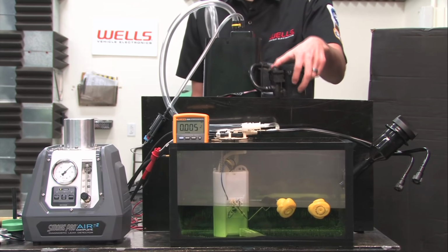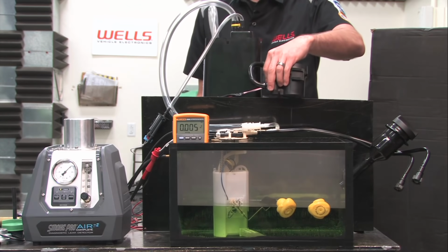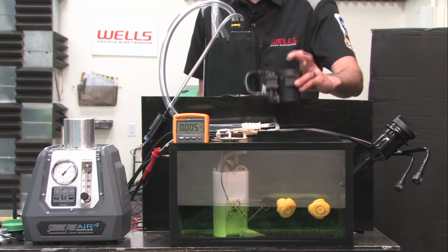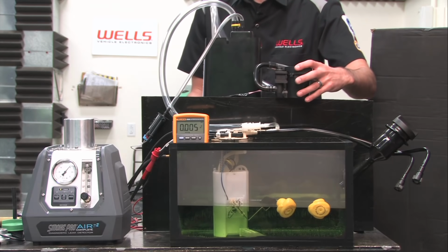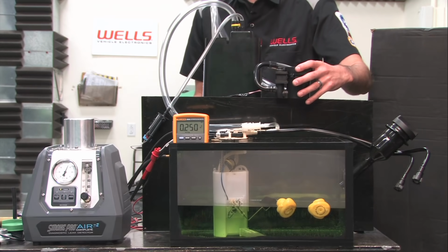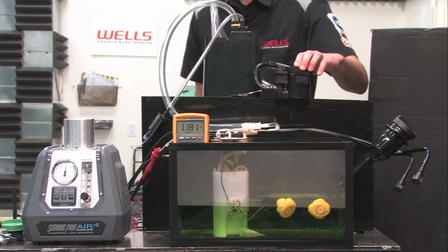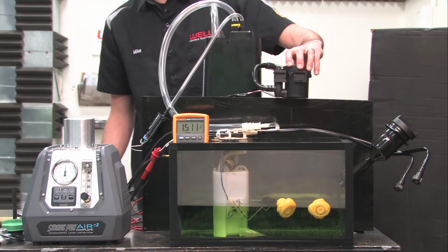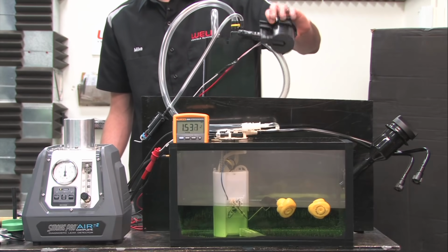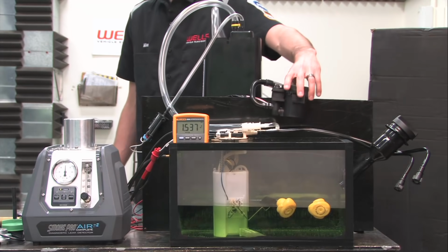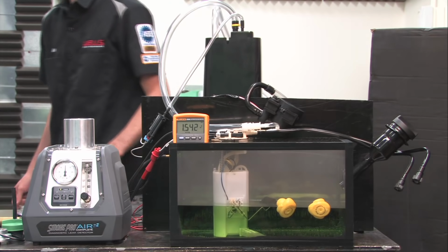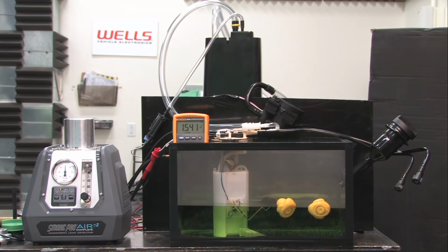And is our vent stuck because I left it plugged in too long? Ooh, she's warm. I think our vent solenoid is stuck. Don't leave your vent solenoid plugged in for 10 minutes. There we go, it just opened. And you can see it return back to atmospheric. So this vent solenoid was turned on this whole time that I was talking, so that is why it probably stuck. And it's also been on this machine for quite a while.